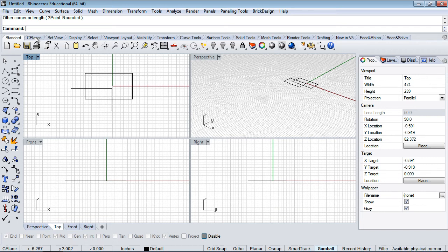So let's say you have an angled roof that you're doing, and it's an angled piece of geometry. You can select that surface and say, this is where I want to create the geometry. So if you're going to build, let's say, a chimney coming off of that roof, you want to have that started as a basis, so you create the geometry on that part, and then build up from that. You can do that. That will get into advanced. Right now, we're just going to look at two-dimensional stuff. So don't freak out. I just want you to understand the concept of it.